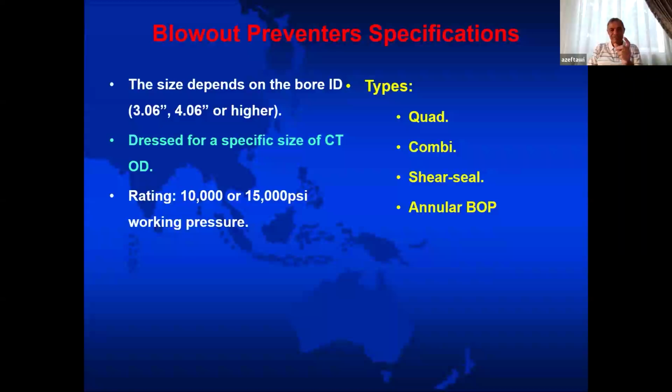The only way that you can use it once again is to send it to the manufacturer. He has to go through a series of tests, and based on that, he tells you if you can use it again or not. And believe me, it is much, much, much cheaper to purchase a new one. It is not a matter of pressure test, gentlemen. The H2S goes through the metal and destroys it.